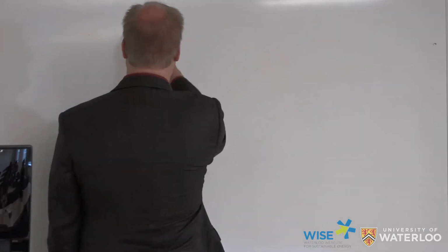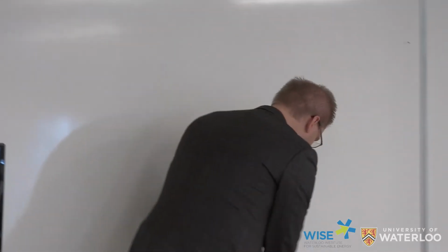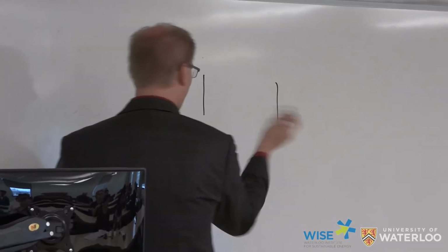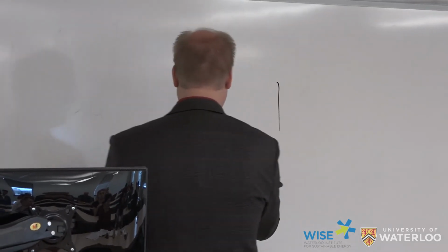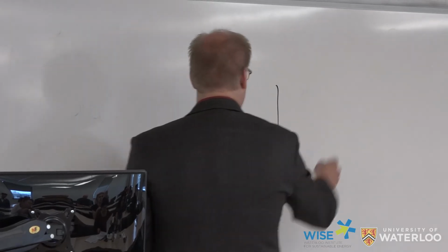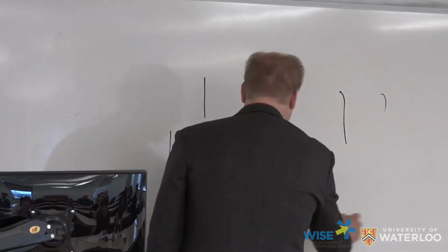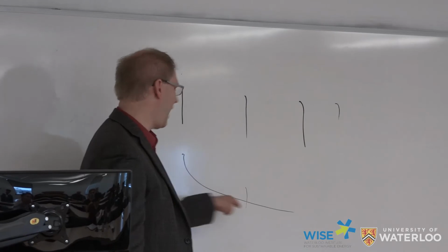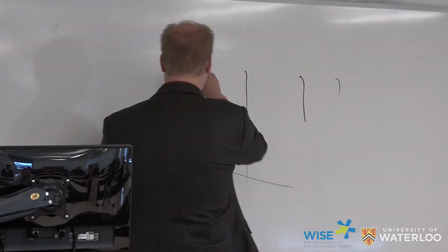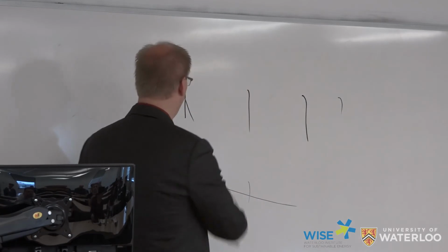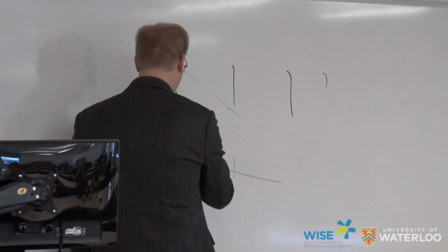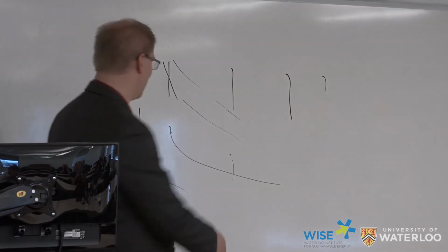Right, exactly. It's probably semantics, but effectively, if you take the standard case, normally you'd say, well, the power of this turbine's here, and if you look down a row, usually it goes something like this, so it drops off really, really quick. Second turbine's about half the power, say, of the first. But if you simply yaw that turbine slightly, then this wake essentially starts skewing like this, and then while this one goes down a bit, this one's way up, and so the average overall is a huge benefit.